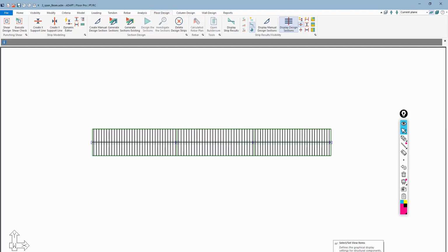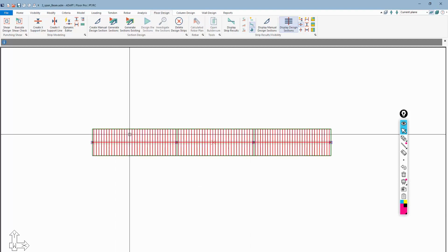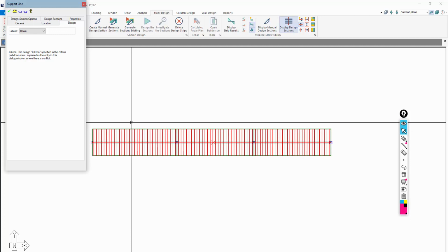And so this beam, we're going to add some fairly unique post-tensioning first. The first thing we're going to do, just for the sake of showing how to model the tendons, and also maybe as a starting point, will be to determine what level of post-tensioning we need, the number of strands we need just to meet pre-compression in the beam. So let's assume our target pre-compression is 150 psi. It's about 0.9 MPa if we're converting it to SI equivalent.